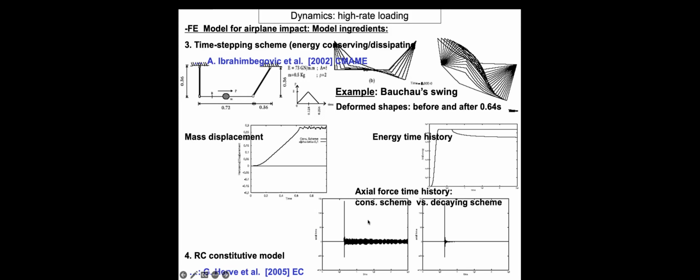Representing high vibration modes with 8 elements, when you need something like 10 elements to represent a typical wave, was almost impossible. So you have some kind of high frequency vibration which never really settles down. So deciding if you have plasticity or not on the basis of such computed stress is not meaningful.